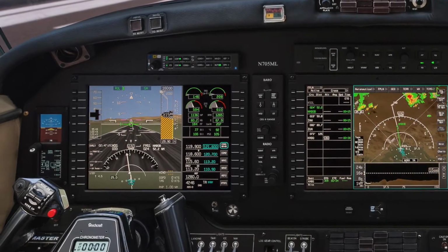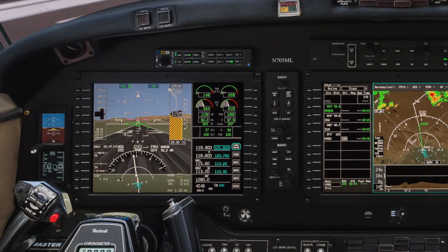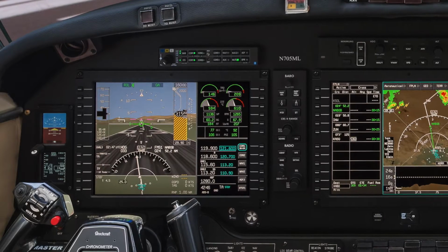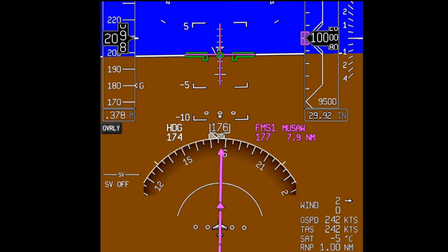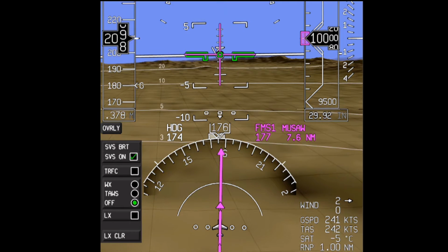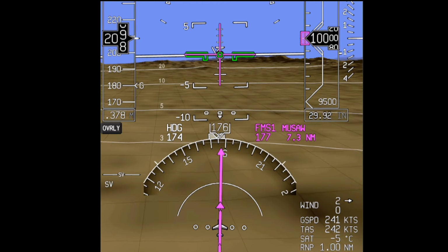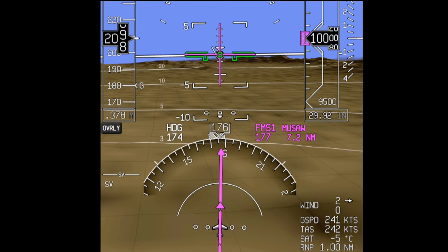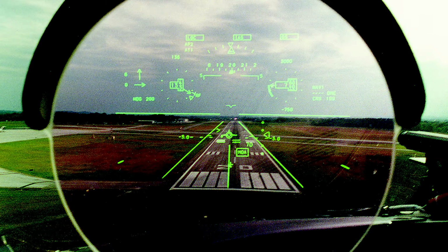The SmartView synthetic vision system on the AeroVue integrated flight deck provides a three-dimensional view of the surrounding terrain coupled with advanced flight path symbology. SmartView starts with a traditional primary flight display and builds upon it by using Honeywell's proven EGPWS terrain database to create a synthetic terrain background. It then adds advanced HUD symbology to the display.